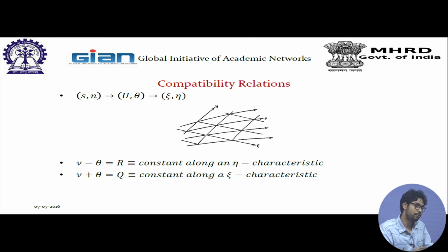Now one thing we need to do is that those equations of motion that we showed are in Cartesian coordinates, but to get the equations in this algebraic format, we need to transfer them into the natural coordinate system. So s is the streamline direction, n is normal to that. These are the independent variables, and u and theta, where u is the magnitude of the velocity and theta is the flow direction, are the derived variables.